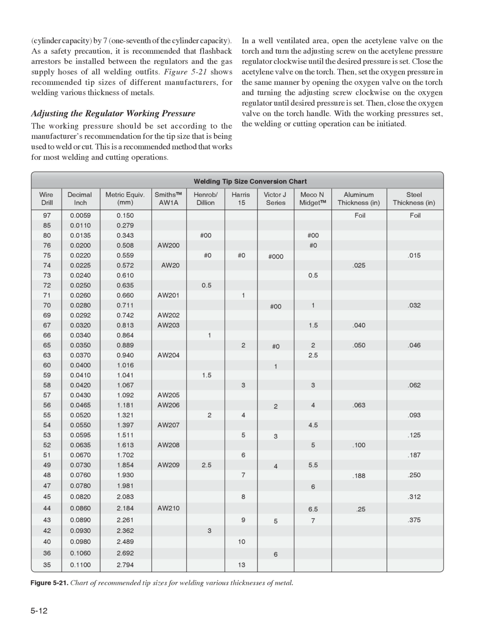The oxidizing flame makes a hissing sound, and the inner cone is somewhat pointed and purplish in color at the tip. The oxidizing flame does have some specific uses. A slightly oxidizing flame is used for bronze welding and brazing of steel and cast iron.